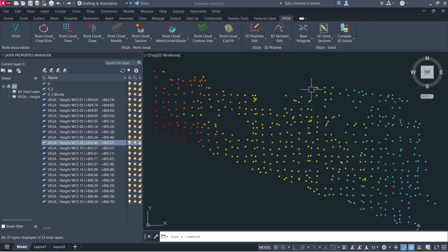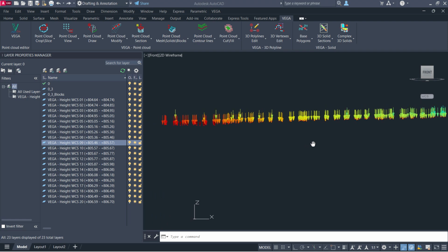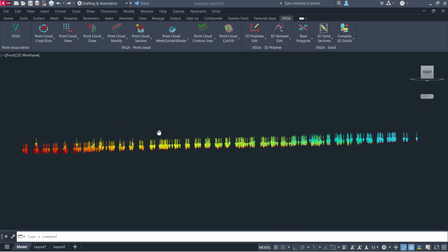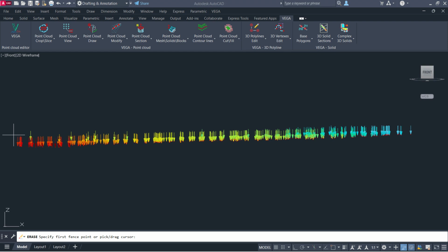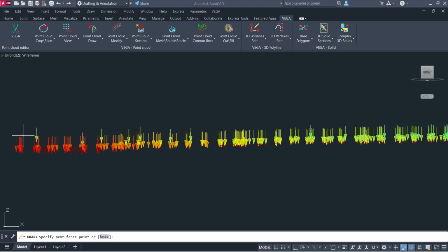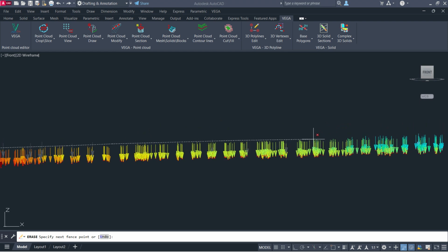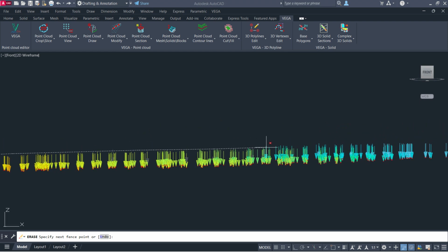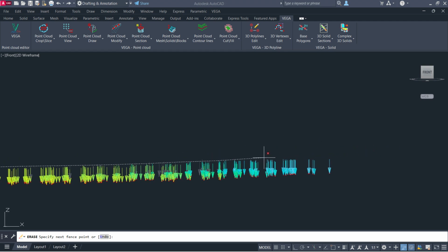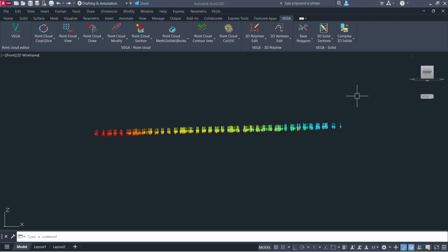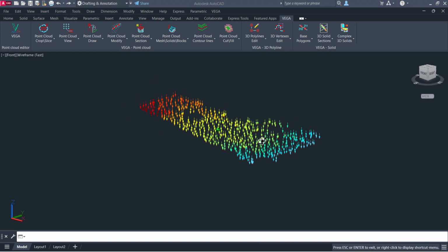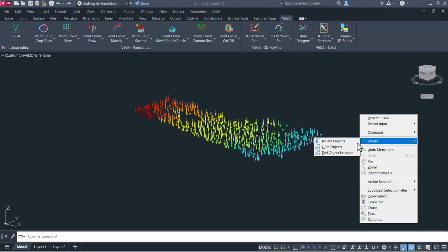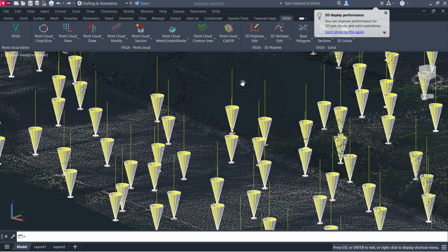In this example, where the surface is not very curved, there is another, faster way to remove unnecessary points. Let's call it mowing the grass. Since our surface is sloped, we set the side view and see everything we need to see. Using the erase command with the fence parameter, we draw a line across the protruding tails of our arrows and erase the unnecessary points. We look at the surface again. We can see that our points are on the surface.